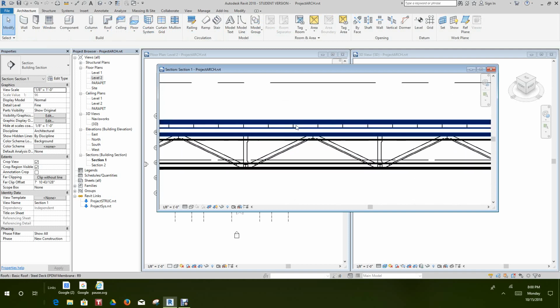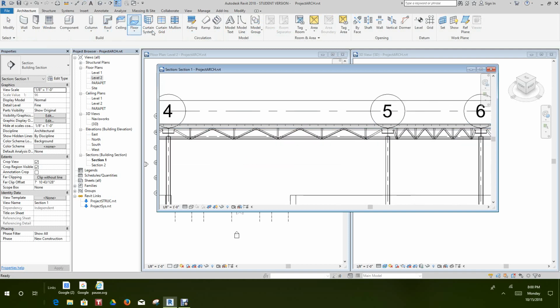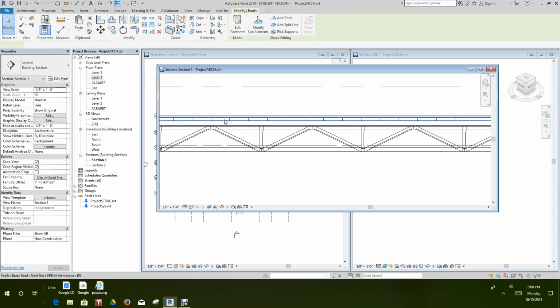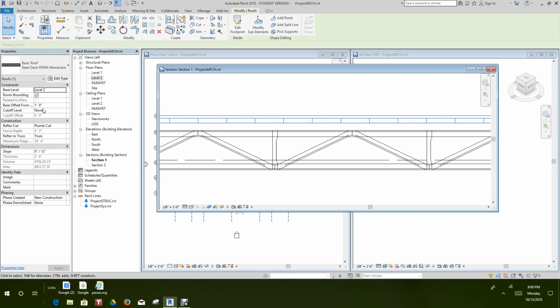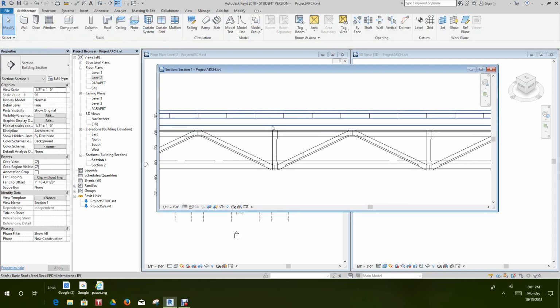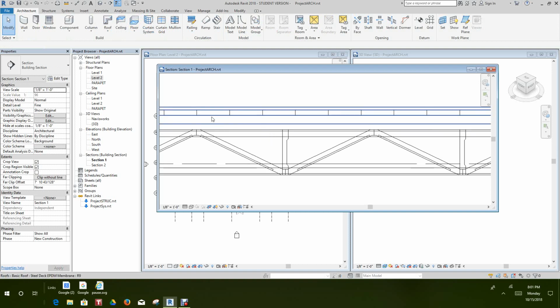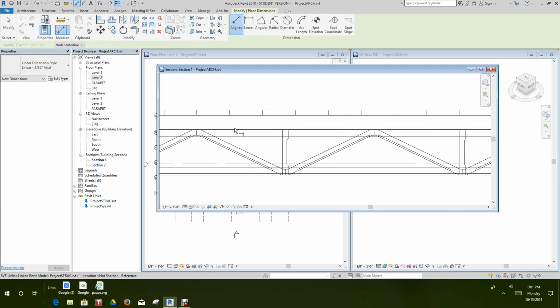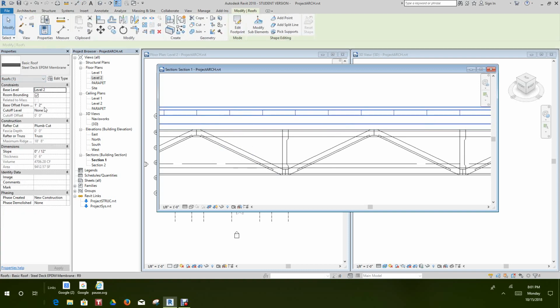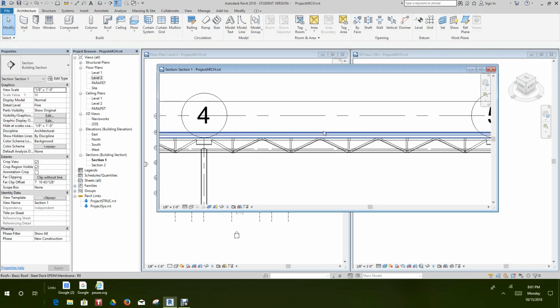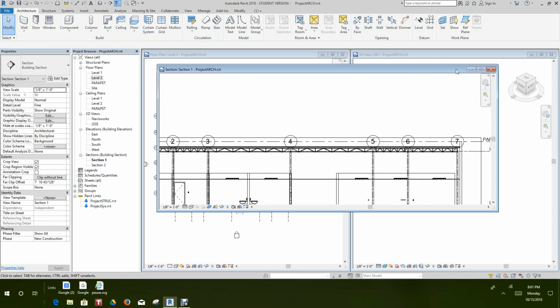Let's look at thin lines and make another look here. I think we should move it up a couple more inches just to clear the joist. Okay, I think we were actually good there with that 1 foot. Let's measure this to see where we are exactly. Yeah, let's drop this back down to a foot. Yeah, because I think we had, yep. Okay, now, there's our roof.